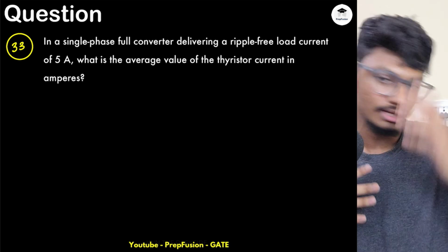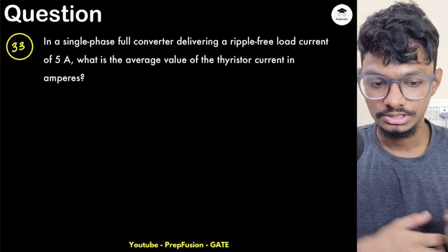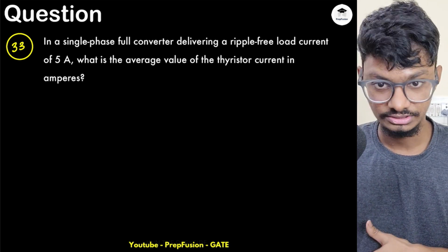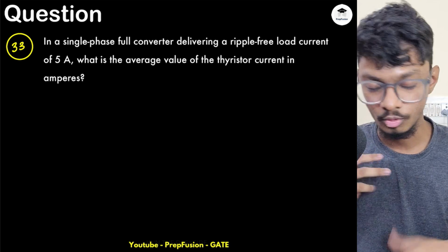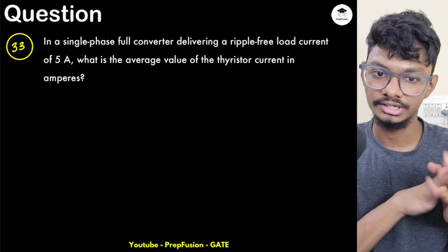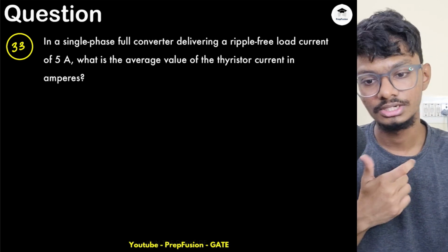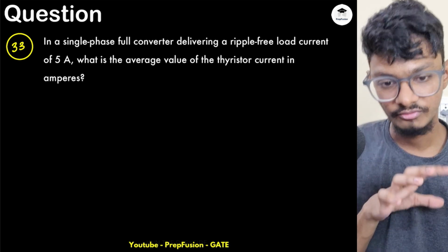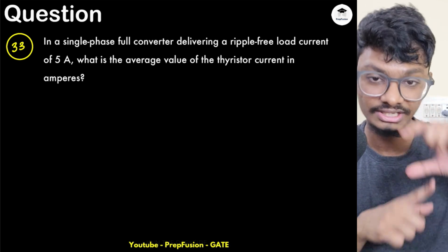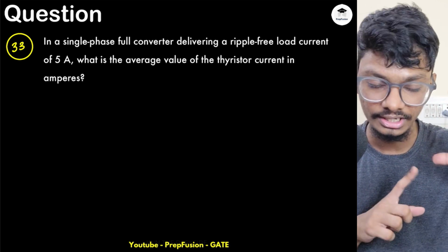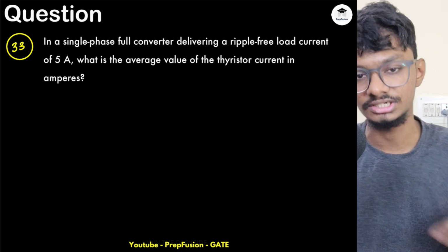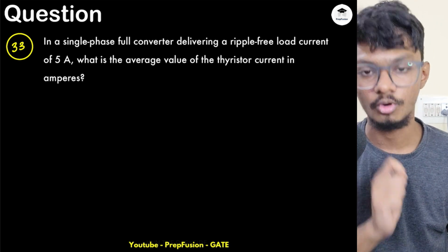If you couldn't understand why this SCR is on at that particular moment, just try to quickly go over the previous course again, or you can understand this in the next lecture where we'll study the semiconductor converter side. There also I will explain this a bit, but if you understood this side, you will be able to easily understand the semiconductor. What is happening? Basically, the inductor is changing everything, right? The inductor is trying to keep a device on so that the current is continuous. That is the most important point here.